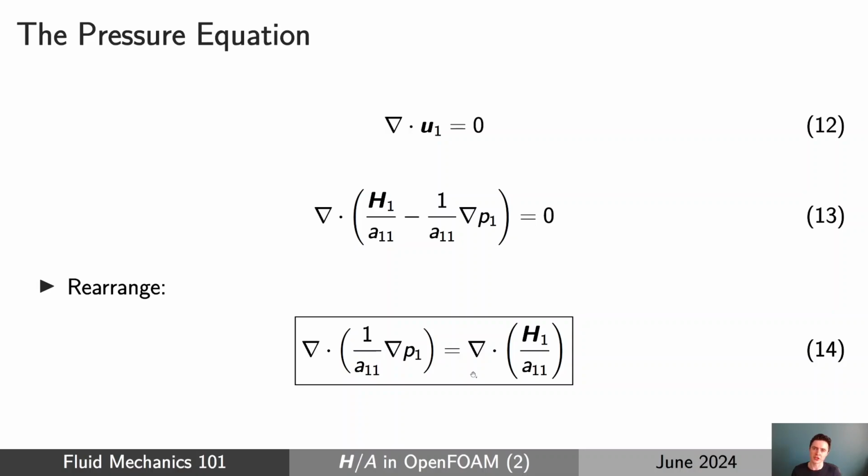And the other small note that I want to make for this pressure equation as well, some of you may notice just the general mathematical form of this pressure equation. On the left-hand side, we have the Laplacian, and on the right-hand side, we just have an explicit source term. There's no time derivative here. We don't have an advection term either. We only have a Laplacian term, which mathematically is similar to the diffusion term that you have in the momentum equation.